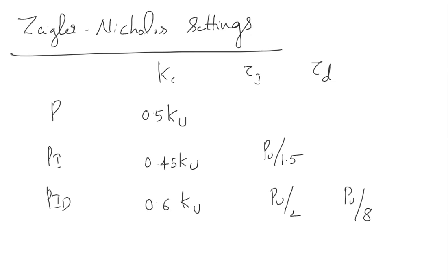But you do all this analysis using a proportional control. That is why when it comes to PI, you use only 4.5. When it comes to PID, you will use, let's say, 6. Let's say my Ku is 10. Then up to 5 only will be used in the plant if it is a proportional control. If it is PI, I'll use 4.5. If you see, I have not written PD.